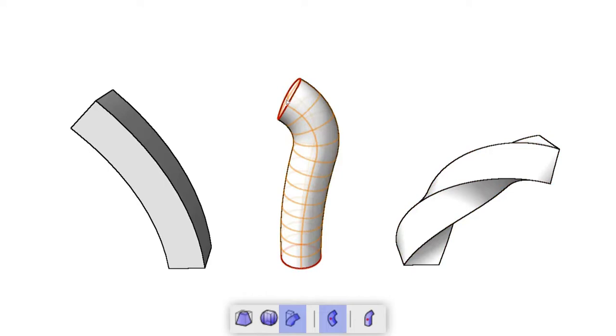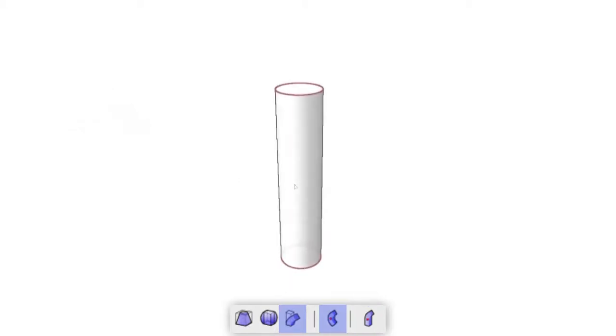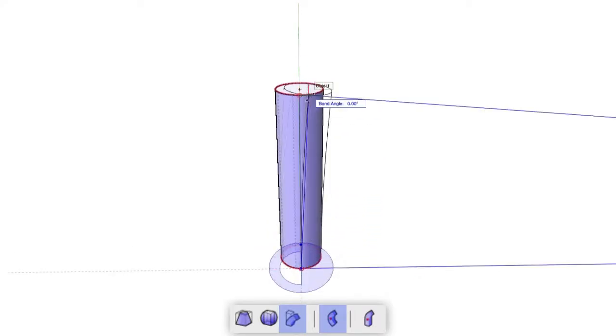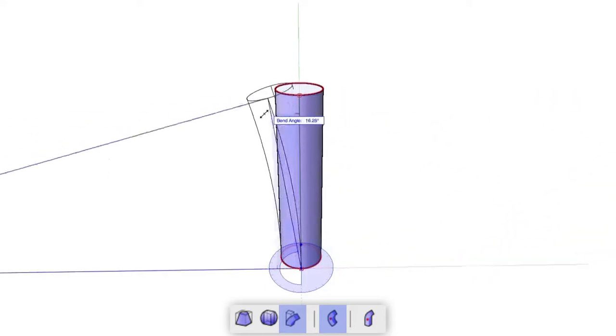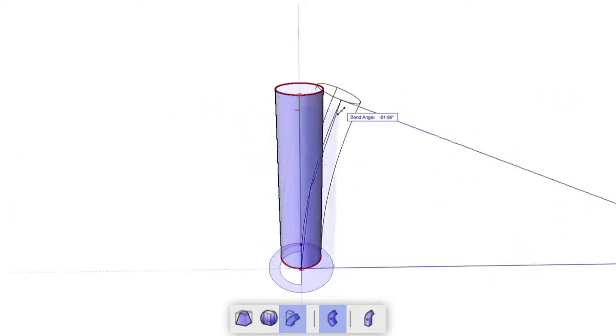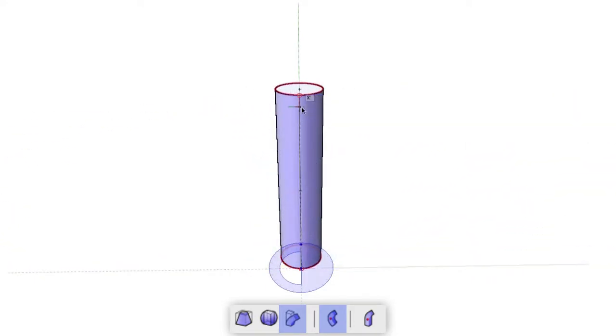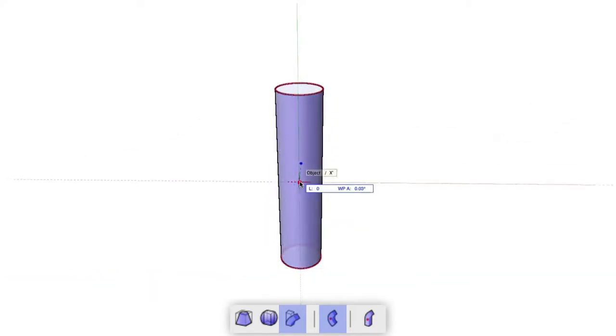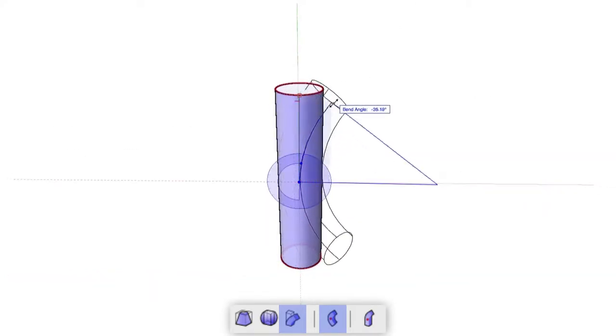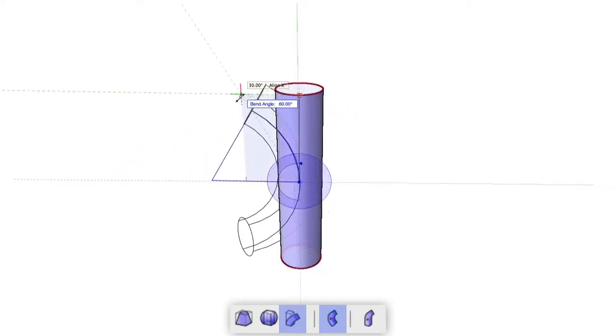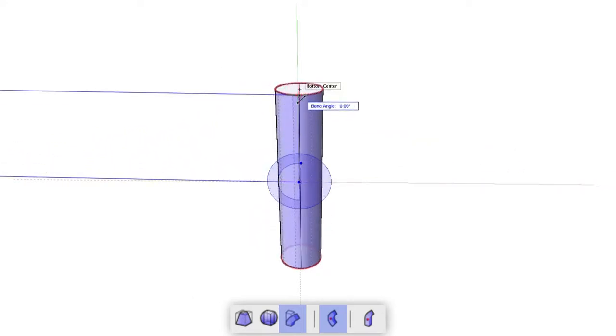Unlike the previous two modes, Bend has another controlled mode, Finite Length, which we will cover shortly. As with the other modes, first select the object. Then, the next click will determine the point where the object will be bent. If you place this modifier at one end or another of a straight object, that end will remain where it is and the other end will be bent. If you place this modifier in the center of the object, the two ends will be bent and the middle will remain in the same location in Symmetric mode.